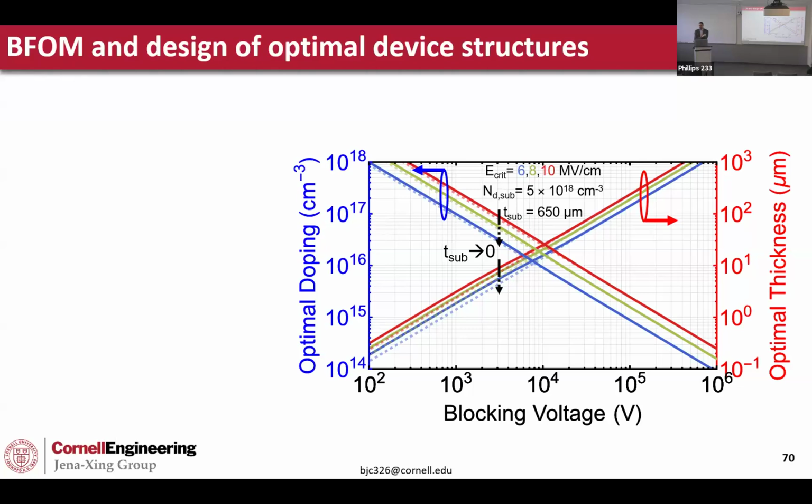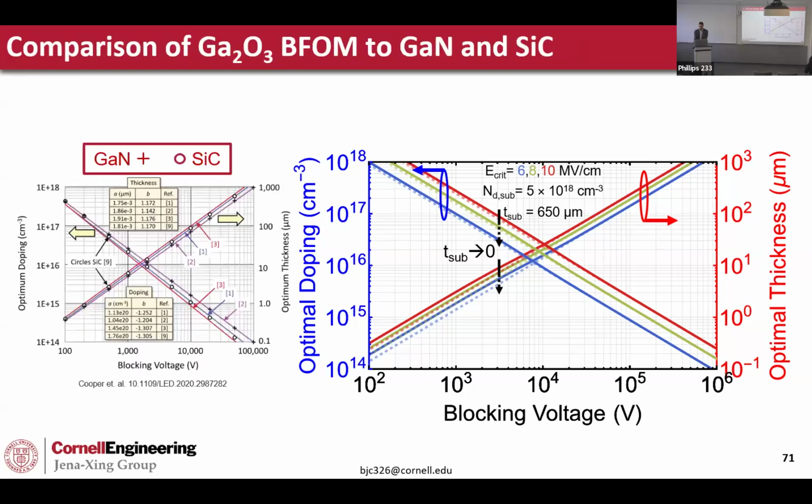And then the other question, you made the point about the benefit. You showed silicon and silicon carbide or GaN. Silicon carbide and GaN, yeah. Yeah. And your point there was the epi thickness, and it's more of a convenience and cost and engineering perspective that you can get away with a thinner epi with gallium oxide. What about resistance and losses though? So if you multiply the thickness times the doping density times the resistivity, is the resistance going to be the same for each of these cases?